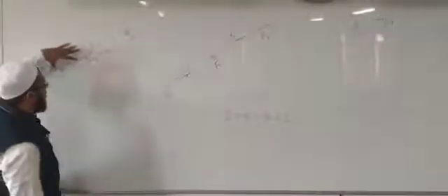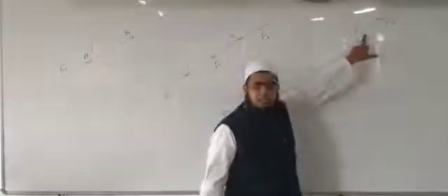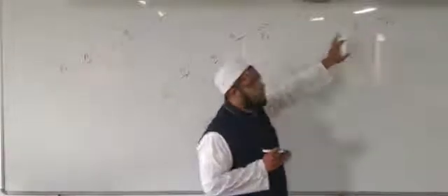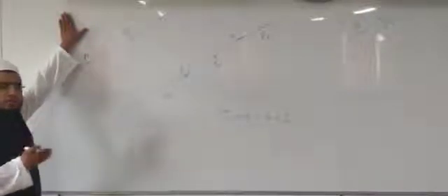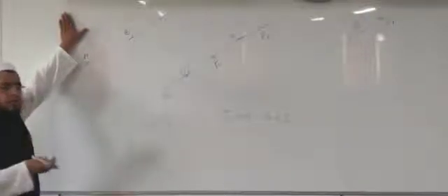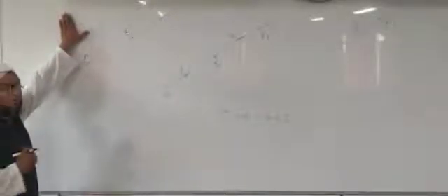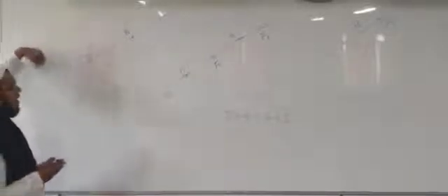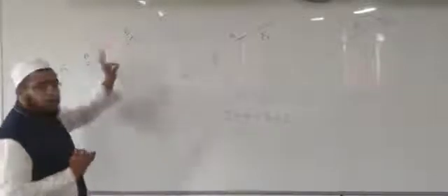You can see that the force F1 which is acting at point A is now transferred to B without changing the system of forces and the effect of the force system. The law of transmissibility of force is used in unit number 2, and in unit number 1 also we will see some application, then in unit number 2, unit number 3, and in the last unit. The very important thing is that along the line of action we can slide the force without changing the magnitude and direction.